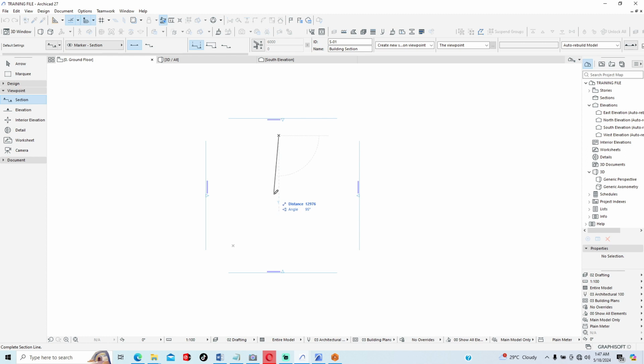For us to have a very straight line or wall that we might be drawing, we need to hold down the shift command. As soon as you hold the shift command, it straightens to 90 degrees, and if we swing our mouse, it cannot move. But immediately we leave the shift button, you can see it sways. We hold the shift and drag to a particular point, and then we click again.